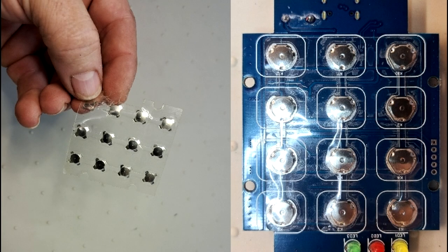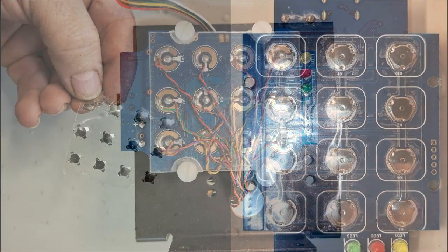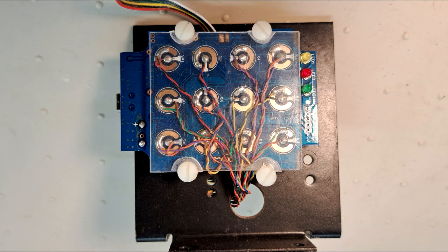You will only need to peel off the blister contacts from the keypad board. They are all on one plastic adhesive sheet. You can solder on your connections without any further modifications. In this example, a clear cover was made. This not only protects the wiring, but also makes it easy to check for loose connections.